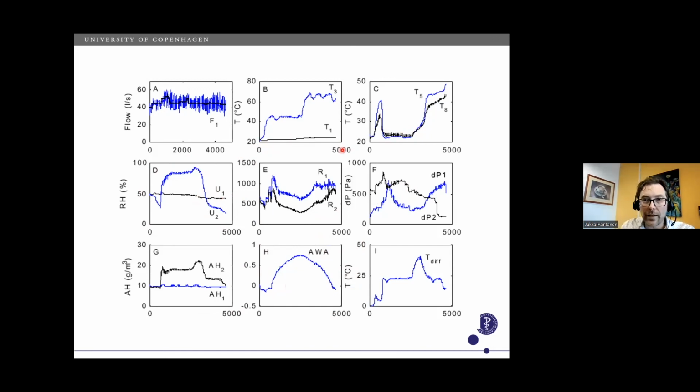So in this specific case, we can see that maybe the most clear signal is the water content. What happens here is that in the granulation process, you start by mixing the powder, and then you add the granulation liquid, and you can see that the water content is increasing. And then when you are doing the drying phase, the water content is decreasing. So this is a fingerprint of your granulation cycle. And then you can see how different other measurements are behaving while you are doing that.